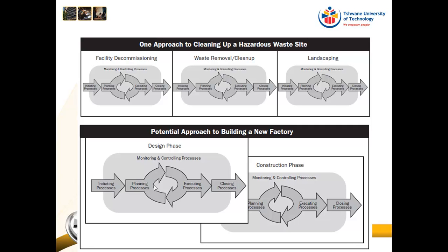We need to use something different, and the different roofing is going to weigh a lot more. That will have implications on our foundation, and that means that although we've already finished the foundation, we might have to do some rework on the construction phase. So yes, it has the advantage of doing things faster, but just remember that it means that you are increasing your risk.